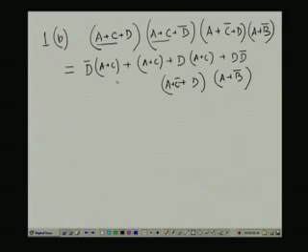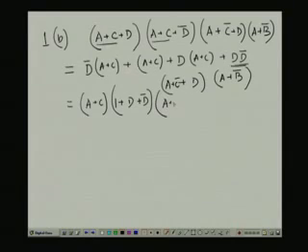Now see that from the first three terms, if I take A plus C common, then it will be 1 plus D plus D bar, and D D bar becomes 0. So the remaining terms will be A plus C bar plus D and A plus B bar.